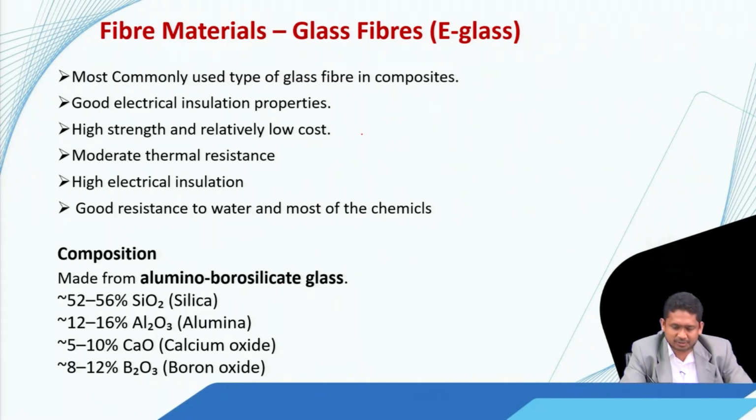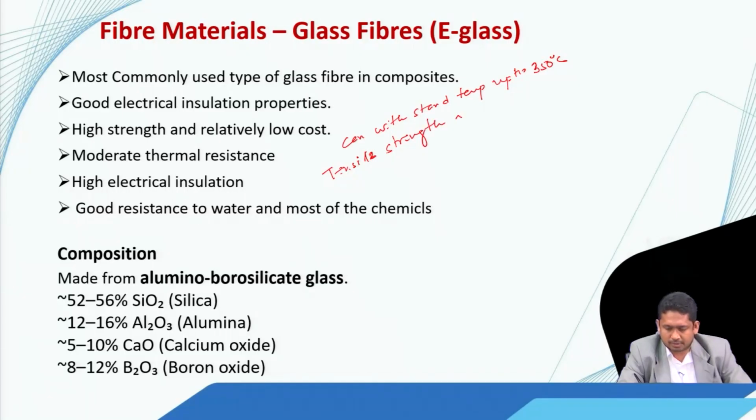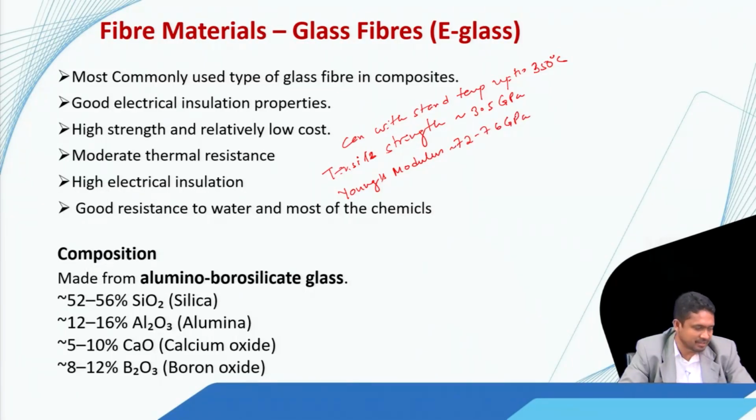If I look at their properties, they can withstand temperature up to 350 degrees centigrade, and they have tensile strength which is around 3.5 GPa, and Young's modulus that is around 72 to 76 GPa.